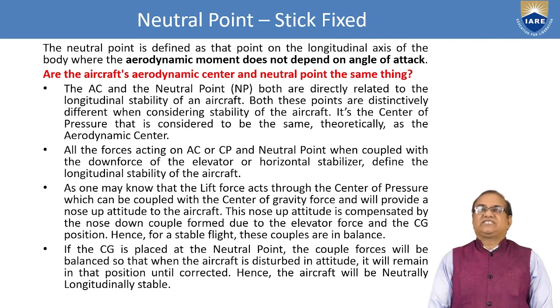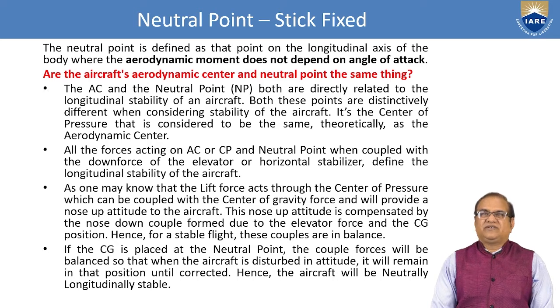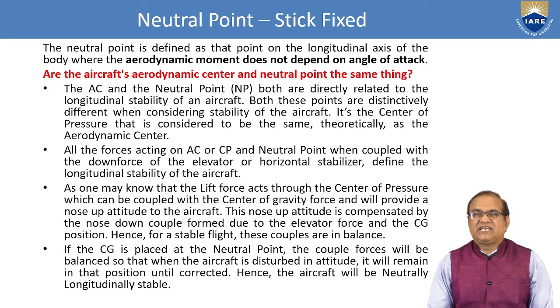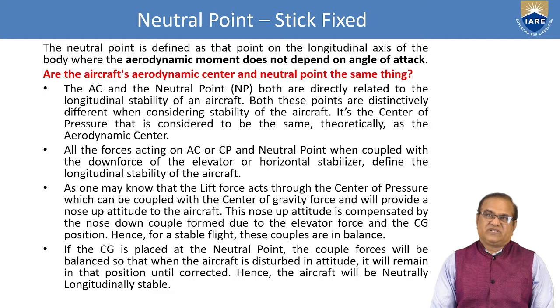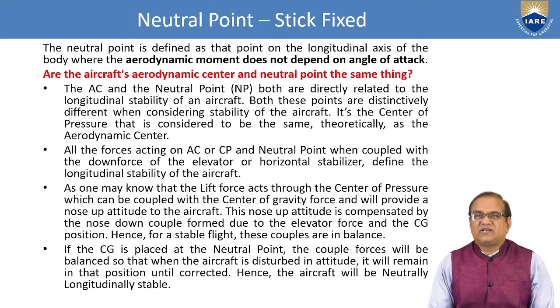Here I have mentioned stick fixed because in most of the cases till now, and further also, we will be studying the stick fixed. Stick fixed means there is no variation of the control surfaces due to aerodynamic forces. It is fixed at one point and it will remain at that point till it is disturbed.